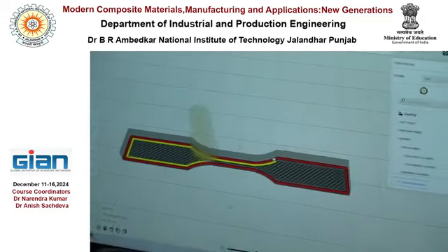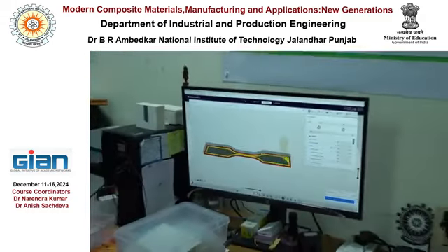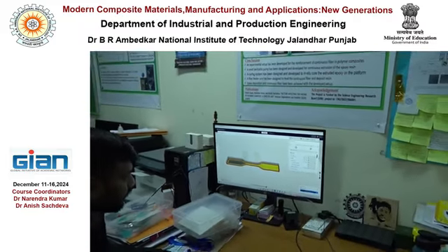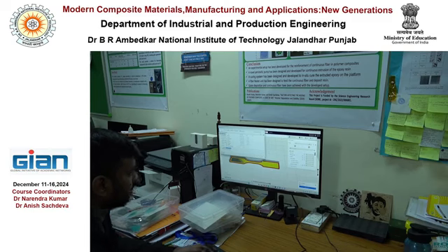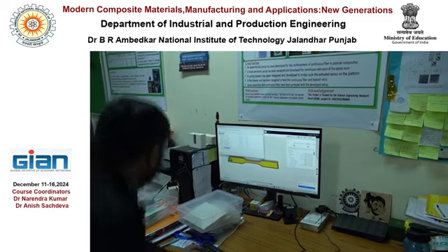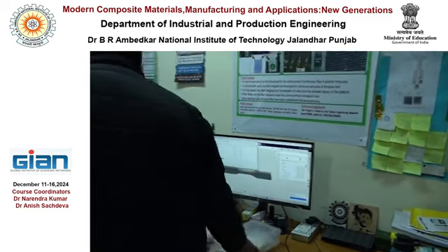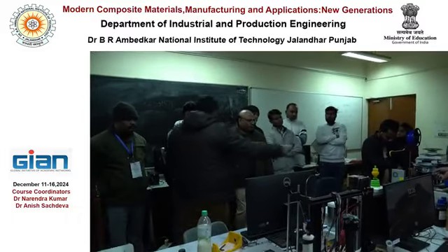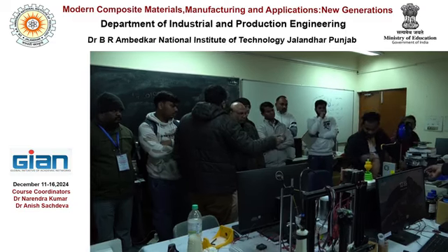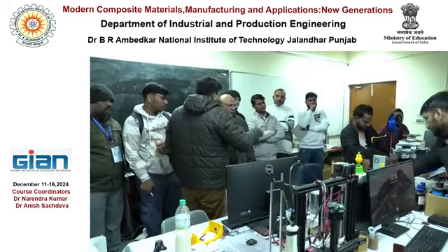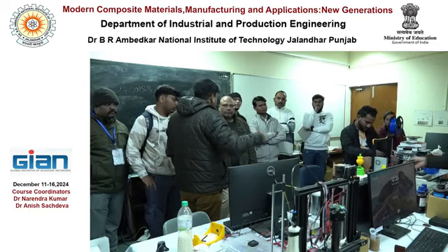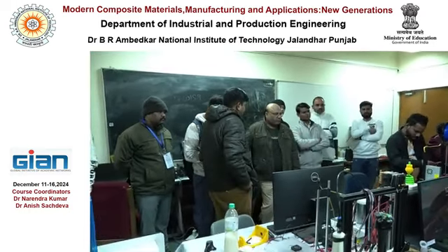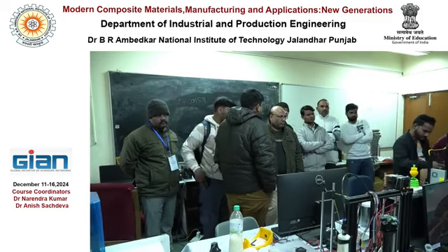Okay, just download the toolpath and upload it to this machine. So now what we are doing? We are going to save this toolpath, and we will take it on a pen drive and upload it to the machine. This is also one way to transfer the file. Or else we can connect the PC. A connection can even be established to transfer the file into the machine.